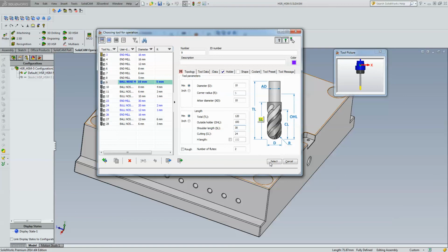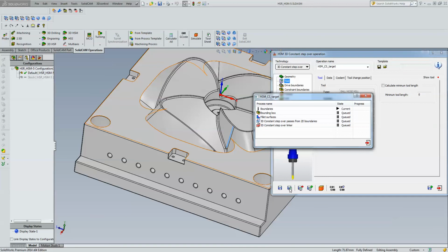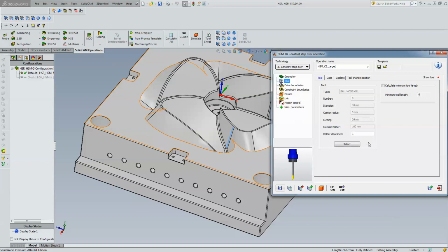And now we're all set over there. Now let's run our calculation. And what's going to happen is the tool will actually work its way in the part. Now, one thing I didn't do, and actually let me stop it for a moment. The way the tool pass is going to work is from the inside out. I'd rather work from the outside in.